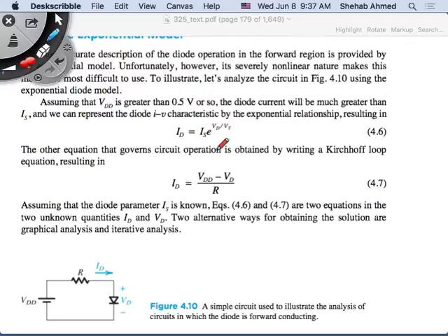So I have this equation from the physics that we discussed. I also have this equation from the circuit. What is this equation telling me? We know that this diode is modeled, in forward mode, as a power supply, a DC source, opposing current flow. Current will flow this way into the diode. The forward drop is a voltage that opposes current flow. Remember we said that I have to be able to increase voltage beyond the barrier voltage to allow diffusion to happen in the diode. This means that I'm modeling this diode as a voltage source opposing current flow.